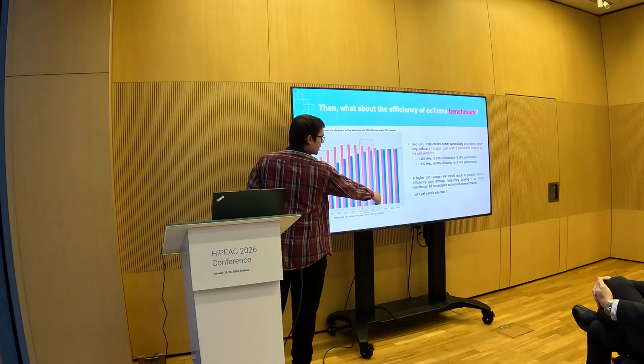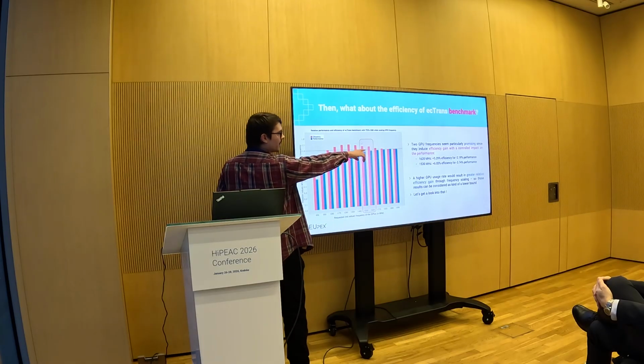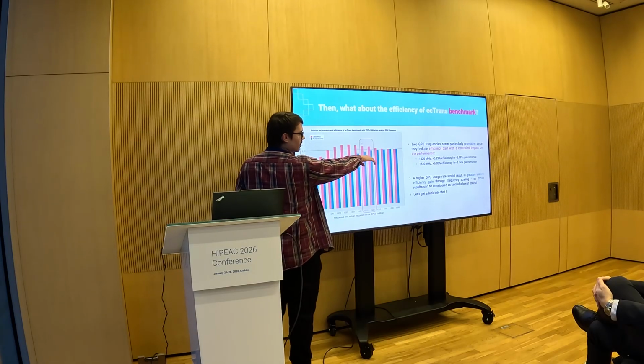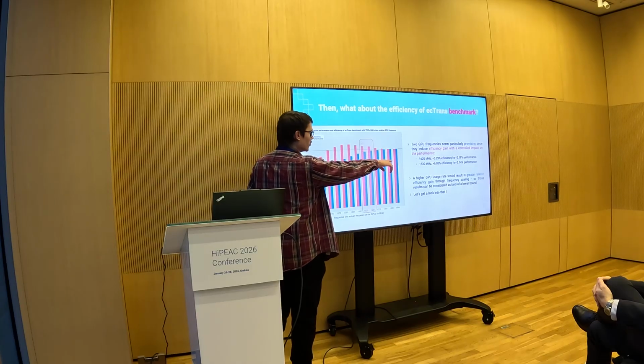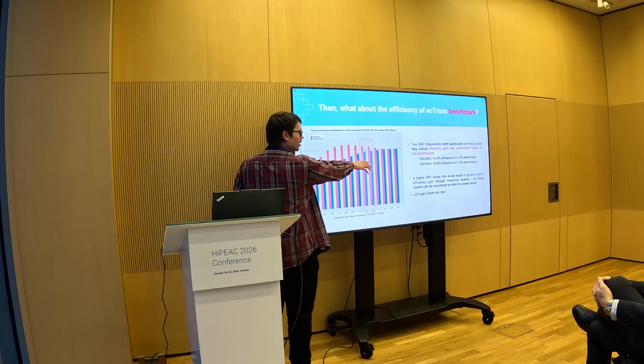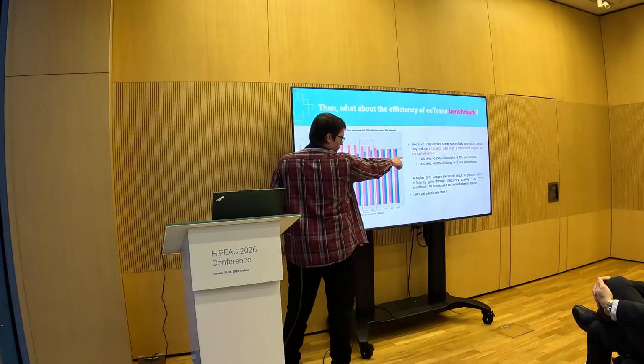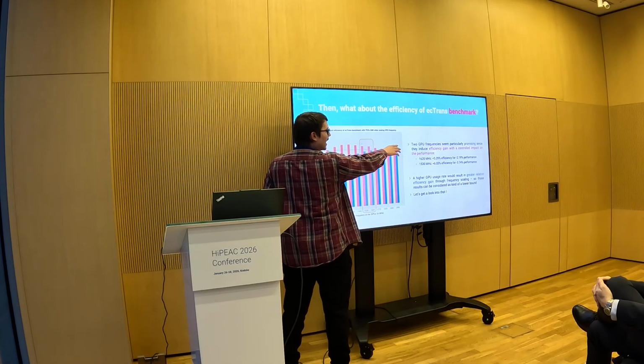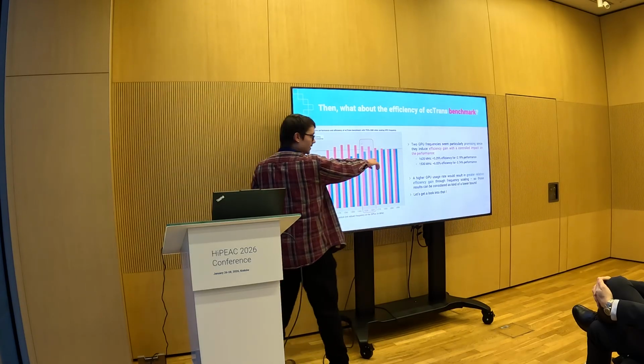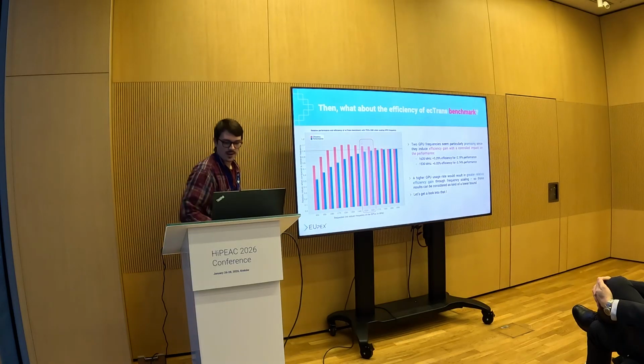For those 2 frequencies, we have efficiency gain, more than 5% at half the cost in terms of performance. So just with a static frequency change, we can leverage quite significantly more efficiency at a low cost on performance. And that's quite a nice result.